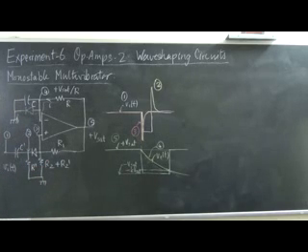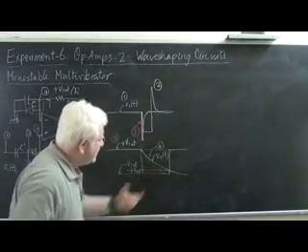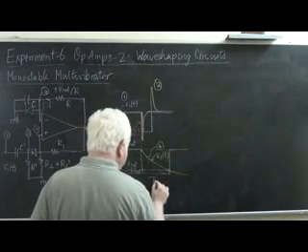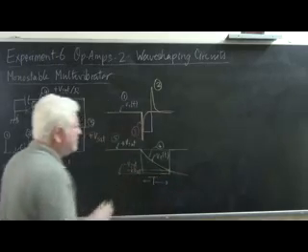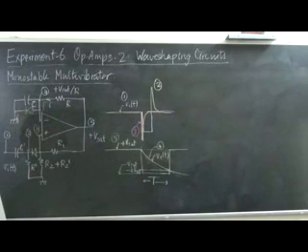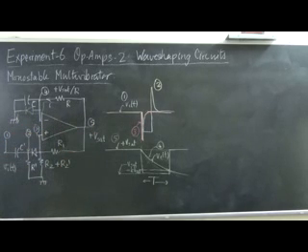What you do when you carry out the experiment is you apply a repeated train of pulses to the monostable, because only this can be seen on an oscilloscope, and at each occurrence of an input pulse you will see that there is an output pulse of a specified fixed width of t seconds, where t is determined by the values of RC and the value of k. So this phenomenon repeats itself over and over again.